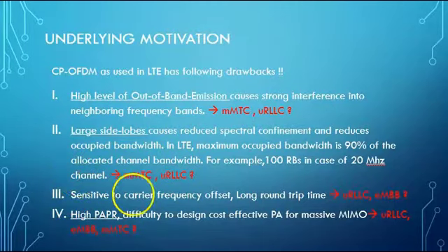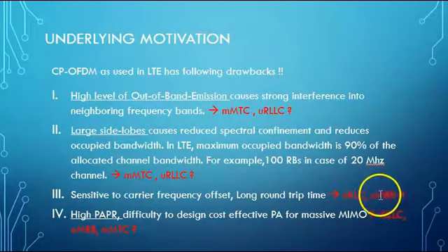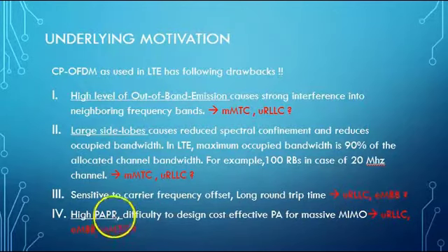Third is the sensitivity to carrier frequency offset and long round trip delay time. If you are talking about low latency systems, and the waveform itself has a long round trip time and is sensitive to carrier frequency offset, then it impacts both use cases, which are ultra reliable low latency communication and enhanced mobile broadband.